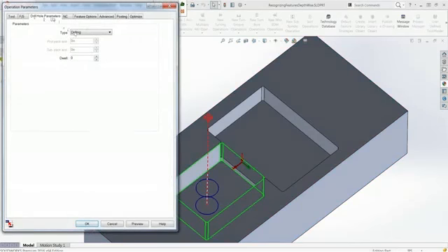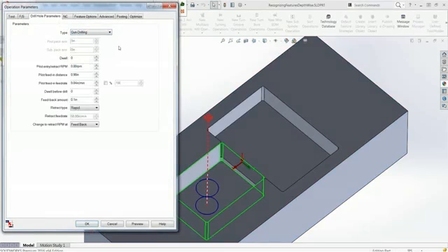And then if I go into this drilling toolpath, choose edit definition, and go into my drill hole parameters, we've now got gun drilling that's available inside of your milling toolpaths, your drill options. So we can use gun drilling. This for sure has to be available in your post processor. So I would double check that you can actually run gun drilling in your post processor beforehand, before trying to run this. But this is now available if you can use it on your machine.